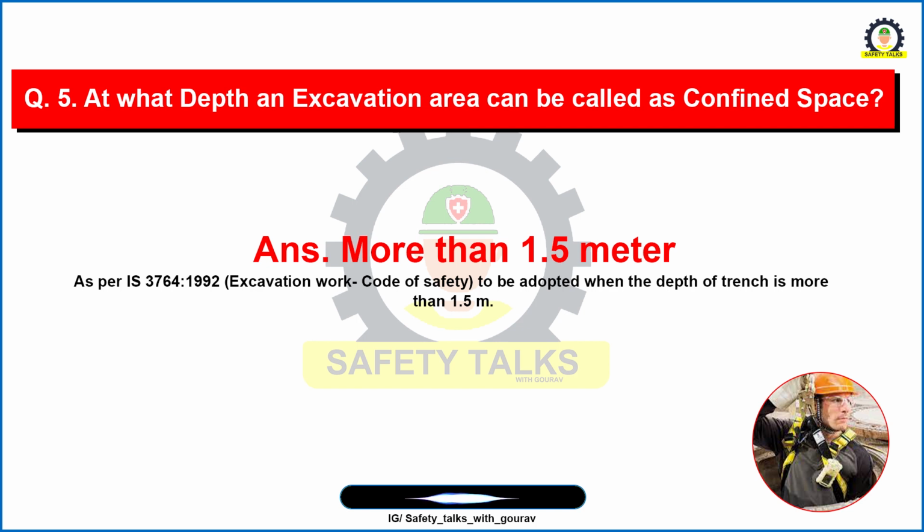In which an excavated area or the excavation area is called a confined space. So the answer will be more than 1.5 meters. Why? Because as per Indian Standard 3764:1992, Excavation Work Code of Safety, it says that shoring is to be adopted when the depth of a trench is more than 1.5 meters. So if the depth of the trench is more than 1.5 meters, it is considered a confined space area. Okay, now next, move on to the next question.